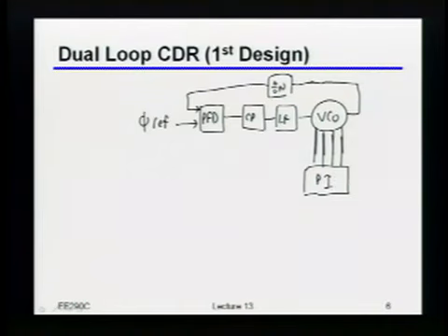So in other words, if I gave you a 0 degree and a 90 degree clock, what I'm going to do with this phase interpolator block is be able to smoothly blend between them to get you phases in between 0 and 90 degrees. Okay? We'll talk a lot more about how you actually do that a little bit later on. But basically, I'm going to be using that really now as a means to actually adjust what the phase really is. Okay? So now we can go ahead and draw the rest of the loop.